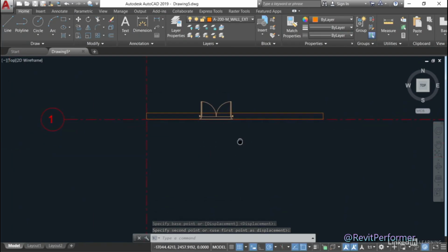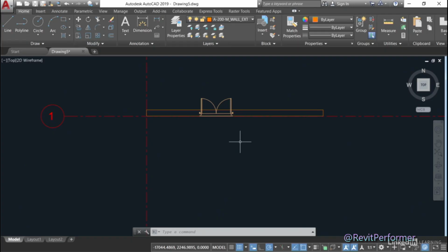Now, I'm not going to draw an entire drawing for you, but you get the idea here now that you're developing a CAD drawing that can be utilized in Revit. But that CAD drawing must adhere to the same standards that you're using in your Revit project. Now, I've been a little bit spoiled here because what I've done is my original drawing, I exported it out of the Revit model and created a DWG from it. But you get the idea. When you're creating your drawings and your templates, they must adhere to known industry standards. And then when you bring them into Revit, those standards are reflected when you're doing your queries on your import instances in your Revit projects.